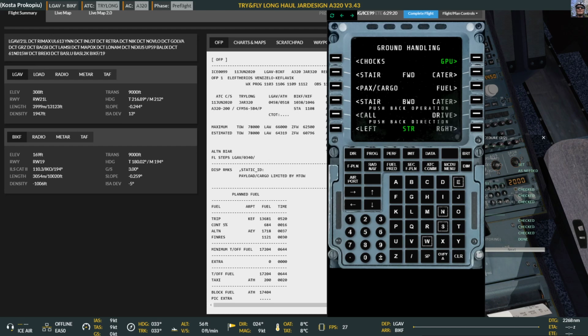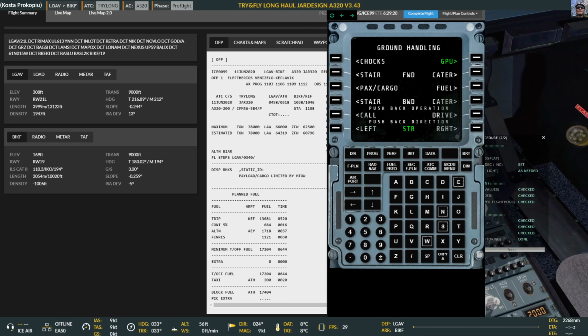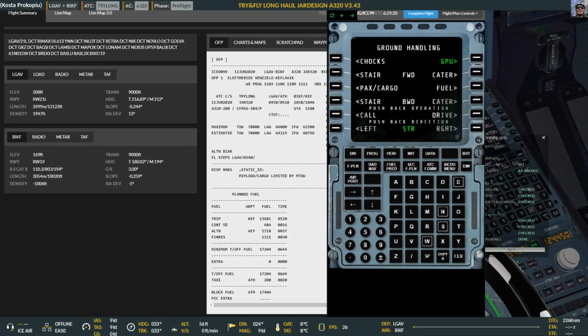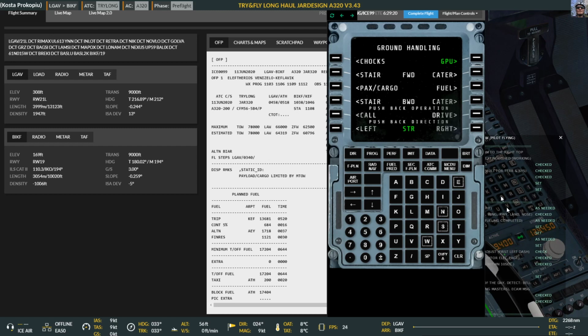So we've done the fuel pre-selection. Oh, that's fine. So on the door page, we also have the crew oxygen, which is fine. On the hydraulic page, we can check that our reservoirs are sufficient. We have low pressure, but I think this down here is the reservoir. They're fine. And on the engine page, we check the oil quantity, which is 15 and 15.1 and 15.3, so that's sufficient as well. And a walk around would normally take place.